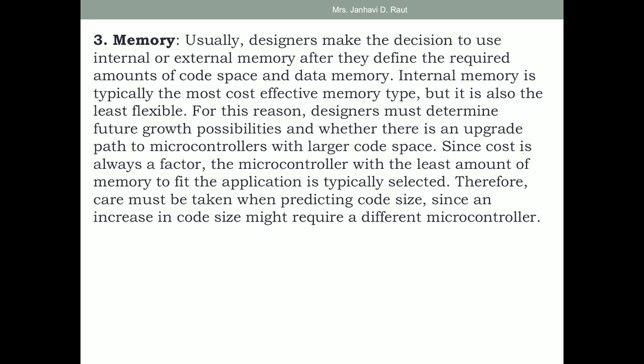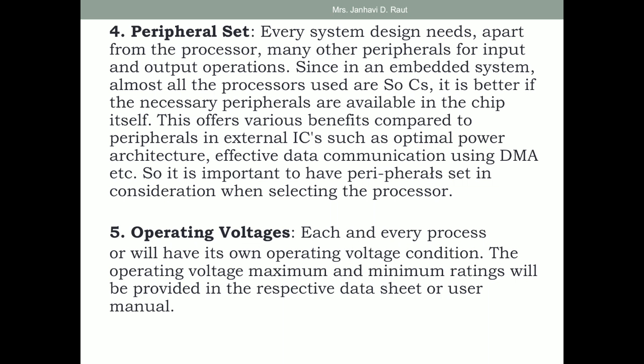Memory. Usually designers make the decision to use internal or external memory after they define the required amount of code space and data memory. Internal memory is typically the most cost effective memory type, but it is also the least flexible. For this reason, designers must determine future growth possibilities and whether there is an upgrade path to microcontrollers with larger code space. Next is peripheral set.